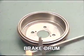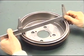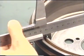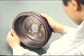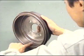Inspect the rear brake parts. First, measure the inside diameter of the brake drum. The brake drum should be replaced if not within specifications. Then make sure there is no abnormal wear or damage.